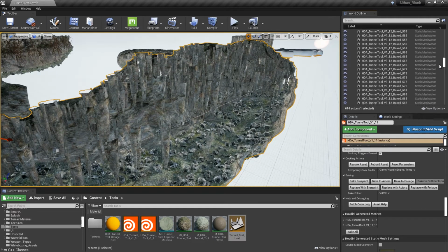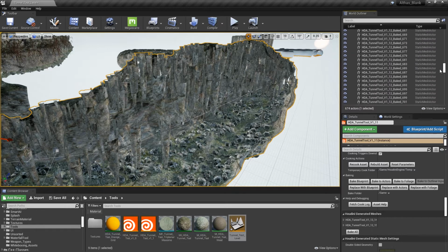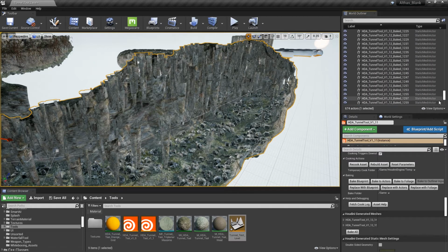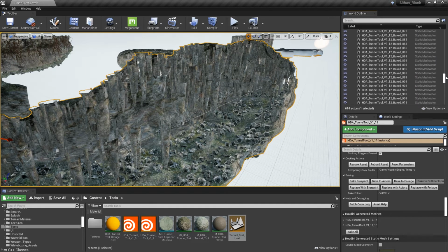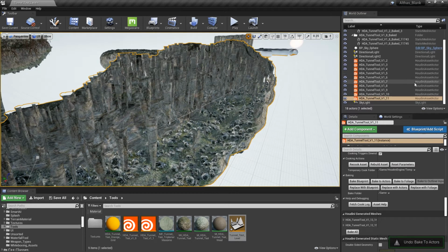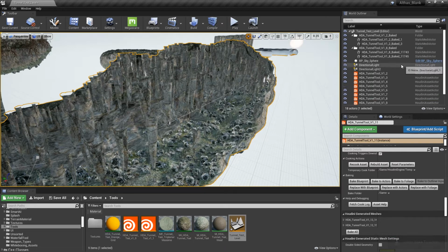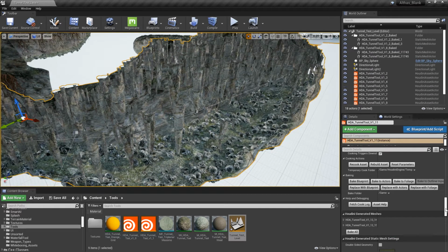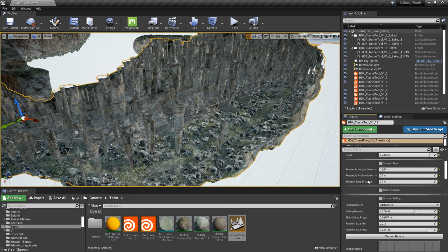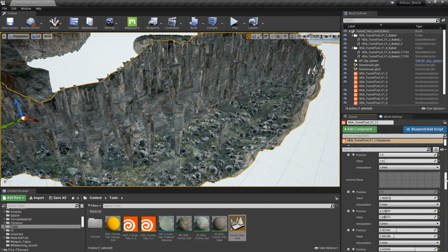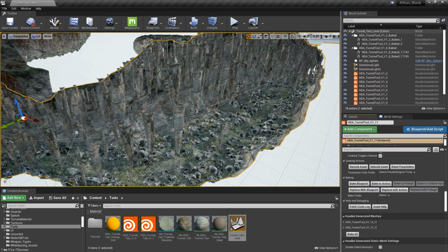So I didn't turn something off because it's baked 1,000 actors. That's what you kind of want to avoid, is doing exactly what I just did. I don't know that I can undo that. I can. Okay, good. So if you notice you've made 1,000 instances, don't do it. Ah, okay. My mistake. Right, going too fast. Bake to actors.